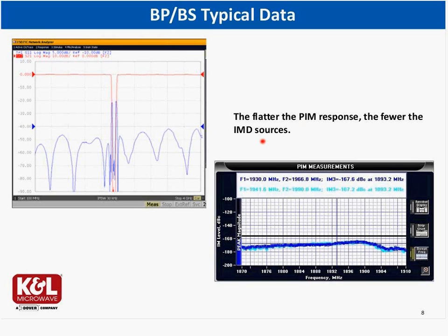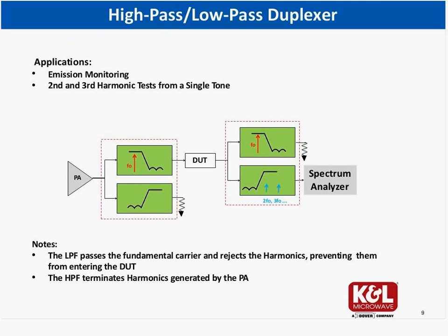They can come in phase and out of phase with each other and give you a baseline before you insert your device under test, which can then reflect in very deep dips, 20, 30 dB deep, even at a point that you would like to read. Bear in mind it's probably caused by another IMD that was out of phase with your device under test. It's important to remember the matter of VSWR matching and IMD sources.